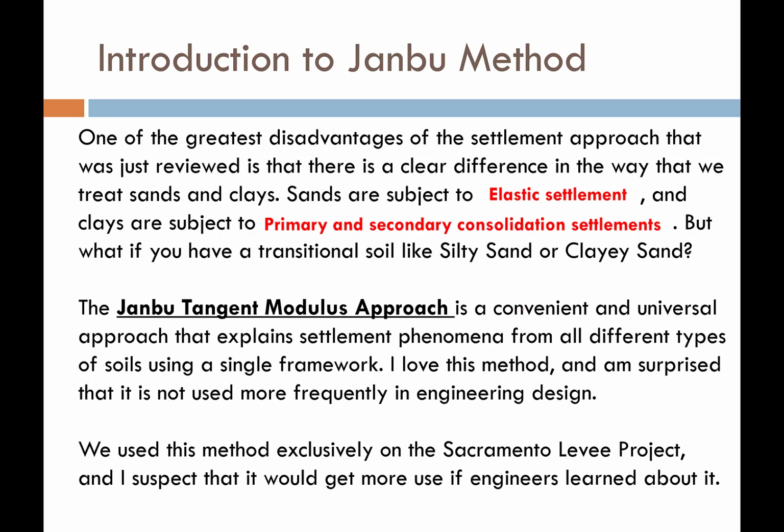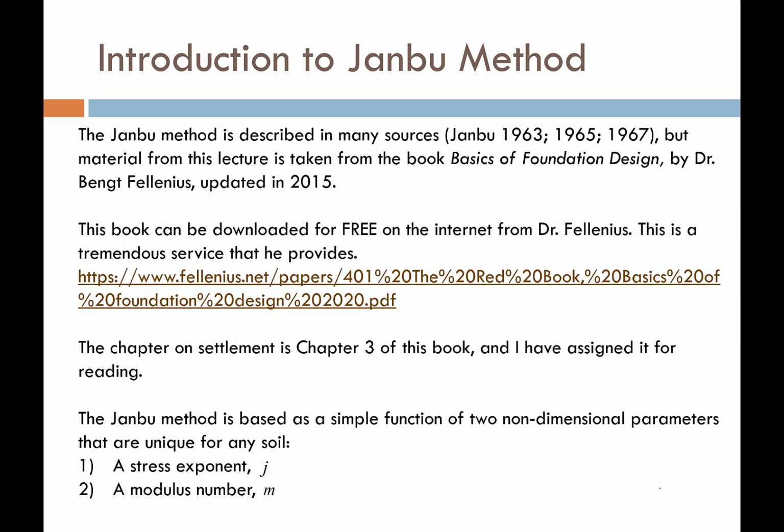When I was a consultant about 12, 13, 14 years ago, I was working on the Sacramento Levee Improvement Project, a massive multi-billion-dollar geotechnical design project, and we exclusively used the Janbu tangent modulus approach to calculate the settlements on that project. I suspect strongly that it would get more use if more engineers were taught about it or learned about it. So that's one of the reasons I wanted to introduce it to you in this lesson. So let's dive in and learn a little bit.